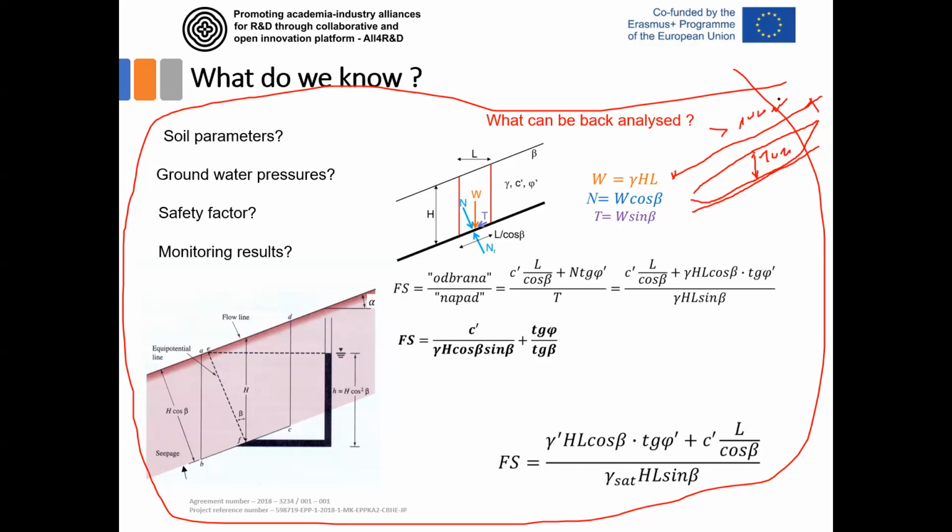There are actually plenty of landslides like this in practice, where you have some bedrock material not prone to sliding, and above it you have some surface material, soil-like material, sandy clay, or similar. What usually happens here, as we said in the first presentation of this course, is that this is a typical sliding mechanism where you have water increment, but the water level increases from bottom to top, since this bedrock material is impermeable.